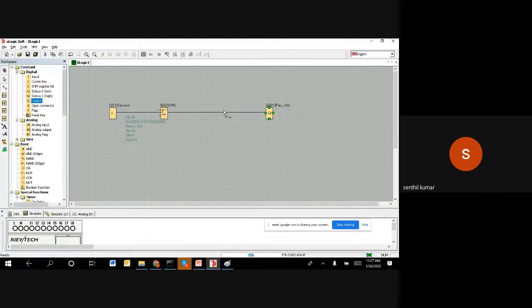If I connect directly, once the 5th bottle is finished, the output will be on. The on is going to be there, though it's going to continuously keep the motor on. But that we don't want actually. What we want is, we wanted to start it, but after 10 seconds, we want to stop it. That is our requirement.